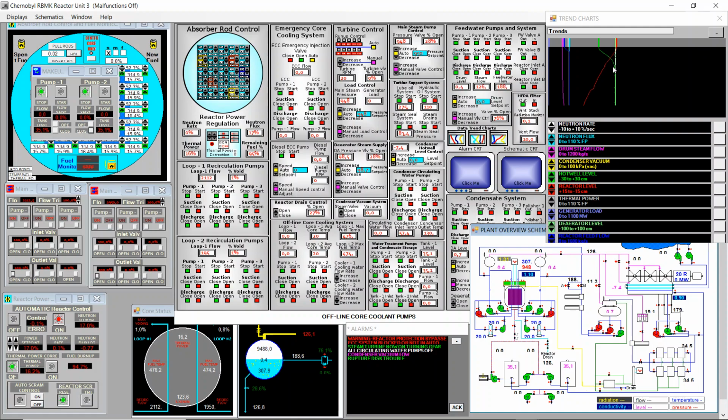Okay, now we see a decrease in the hot well, but it seems transient. Okay, so as I was saying, as a thermodynamic system, we were generating a lot of heat in the reactor. We're at 16% of thermal power, and there was no heat going out from the system anywhere, except from the ruptured disk. Okay, this could serve as a discharge valve for the steam being released into the atmosphere, and this could alleviate the excess heat in the system. I'm not sure about that.